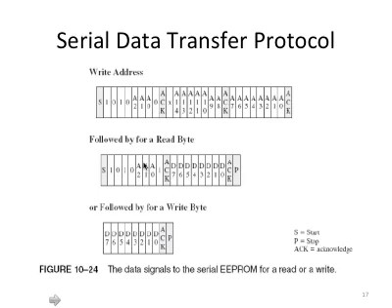So what's happening in the first example is that after the master, the microprocessor, puts out a start signal, it will then output a special code, this 1010, followed by A2, A1, A0, and then a 0.